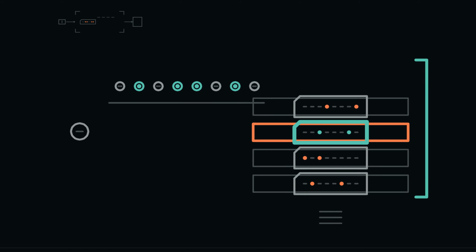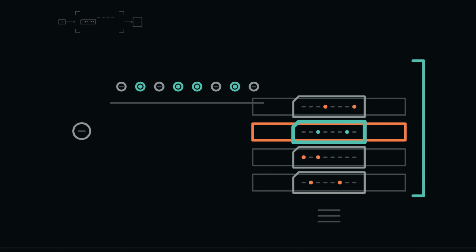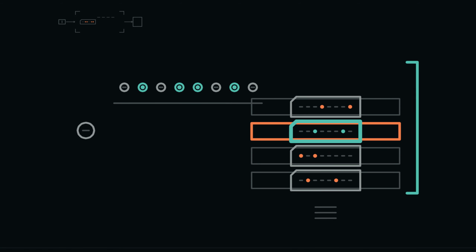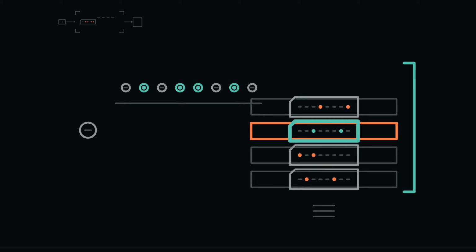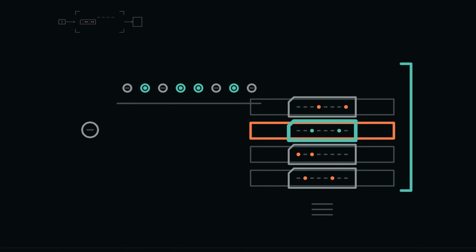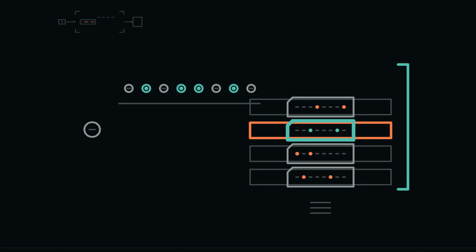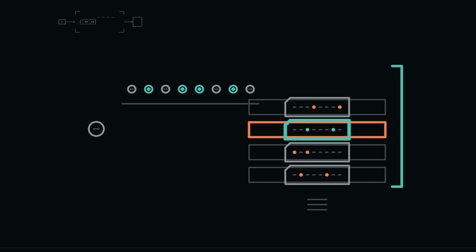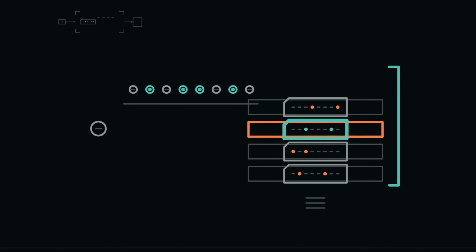We can now scale without animating every storage cell one by one. The rule is explicit. There are 8 cells per byte row, with bit position preserved. Each memory row address has one decoder output connected only to that row. A write changes exactly the selected row. A read changes no row and exposes exactly the selected byte.